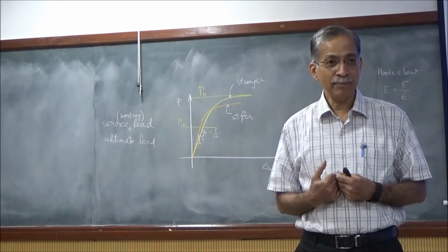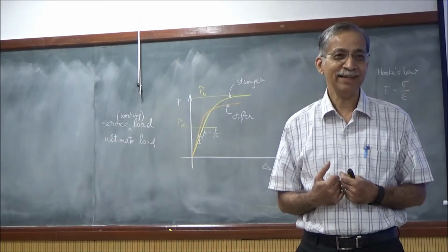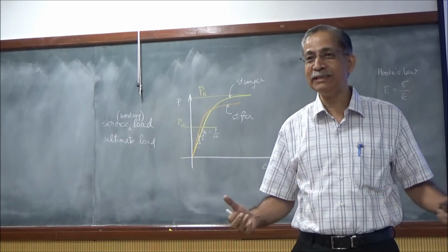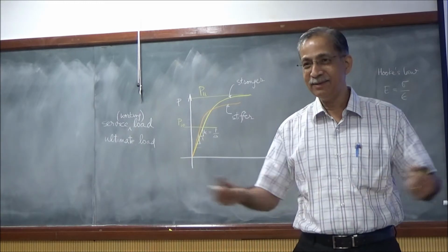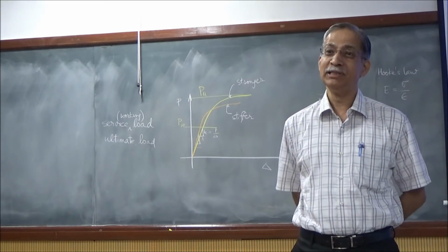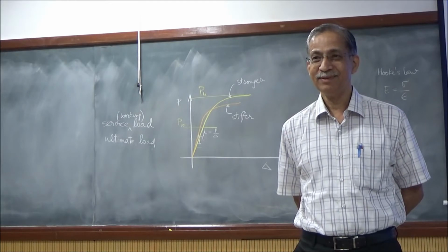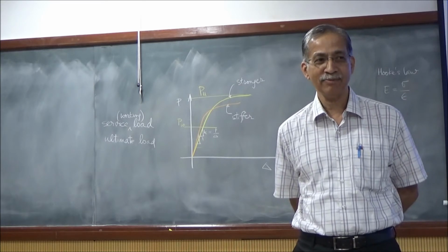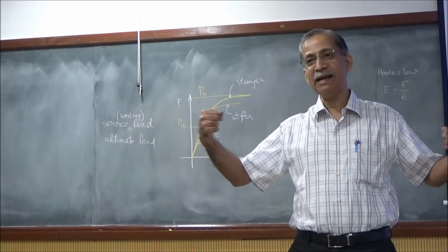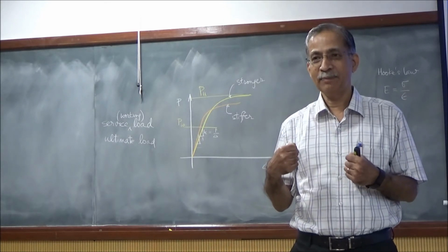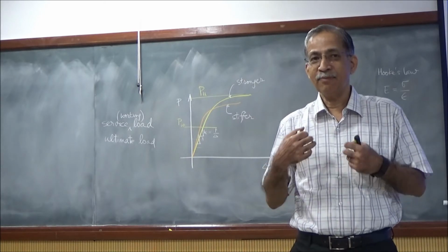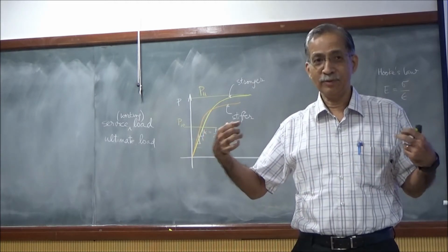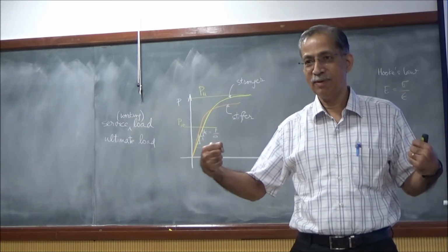So, which is more elastic, rubber or steel? That's a tough one. The layperson will say rubber band. But structural engineers say no, steel has a higher modulus of elasticity than rubber. What do we mean by that? Then you have to have clarity. In both cases, it regains its original shape. But the force required to stretch steel for the same elongation is much, much more.